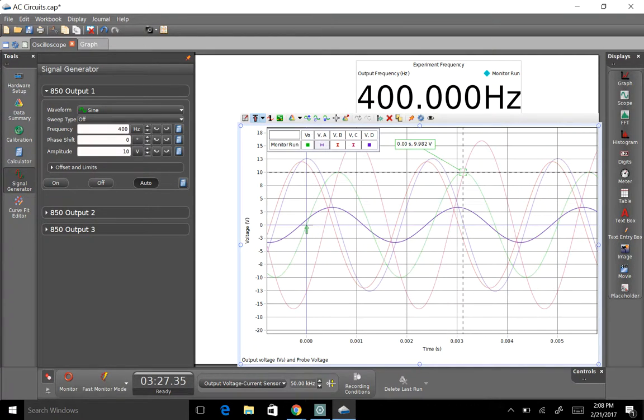Then we'll go to the voltage across the resistor. So put V with a subscript of capital R. So the voltage across the resistor has its peak of, that doesn't seem right. Come on. Three point 3.337, which I would say 3.34 plus or minus 0.01.